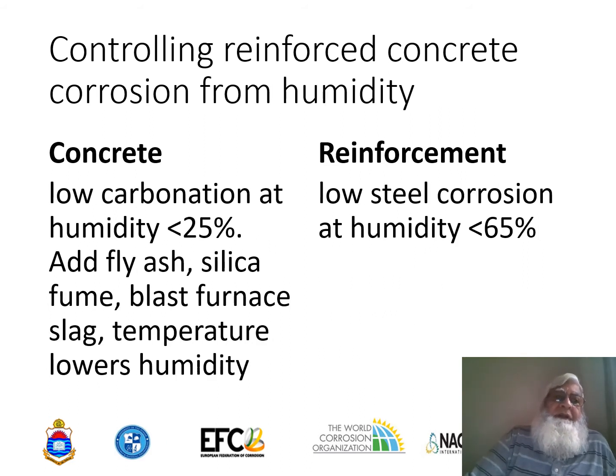Controlling reinforced concrete corrosion from humidity. Humidity plays a very great role in initiating the corrosion of the concrete itself as well as the reinforcement in there. Carbonation starts or becomes significant only when the humidity is more than 25%, whether on the surface or inside the pores of the concrete. In order to prevent or lower the humidity further, right?